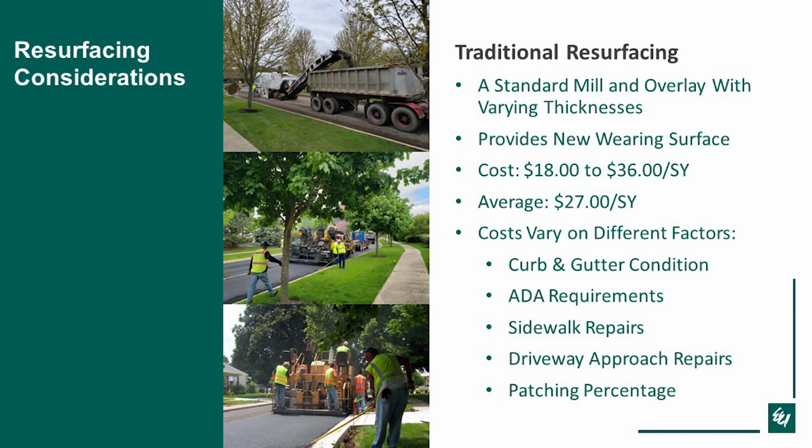So the patching percentage, that's where, as Tim talked about, with that pavement management data, we'll be able to tell you if you think you have base problems or you might have base issues, you can do that heavy patching to try and fix that base, which is traditionally going to be cheaper to do it that way than just remove and replace all of the existing subgrade.